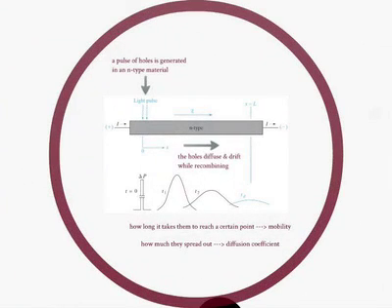The experiment is very straightforward, but to do the measurements is a little bit tricky. So it's again the same example that we saw here. We have a long semiconductor bar, and a current is flowing. You apply voltage, a current is flowing, just like before, that's the drift current. You generate locally a pulse of electron-hole pairs, and this could be done a number of ways, and we'll talk about two ways here.